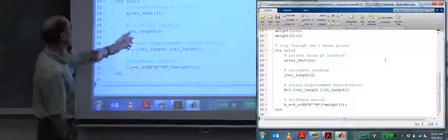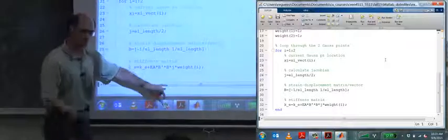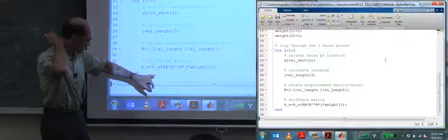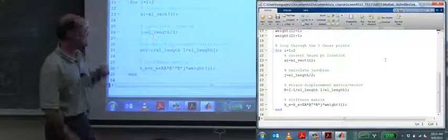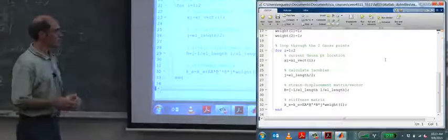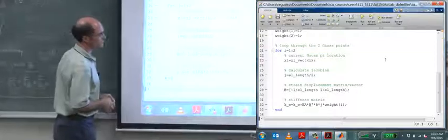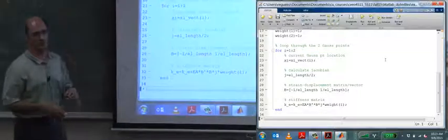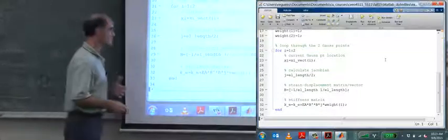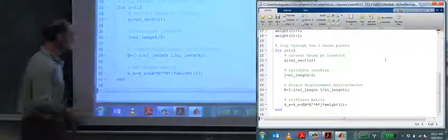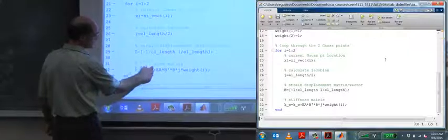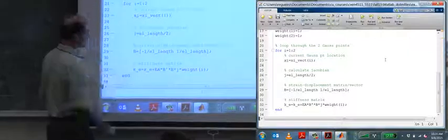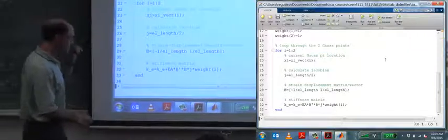It turns out that all of these values are constant, except that for the next problem, the next element that has a quadratic cross-sectional area variation, this will then be evaluated at the integration point. Oh, I'm sorry. That must be why I chose the Gaussian quadrature of 2, to integrate that exactly. Now I'm trying to remember. Because if the area were constant, 1 Gauss point would have been sufficient. So you see that you assemble the stiffness matrix as the value at 1 Gauss point plus the next one, and you get KE. Okay? So that is how you would assemble one of the constant cross-sectional area ones.